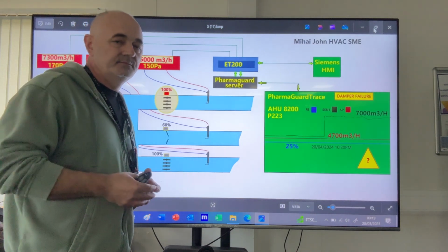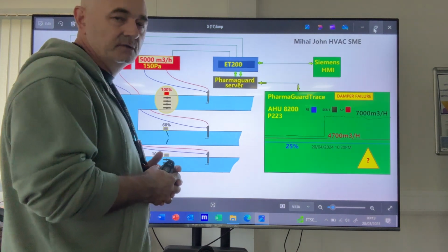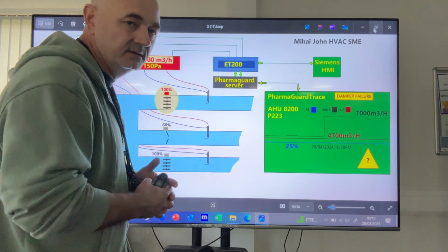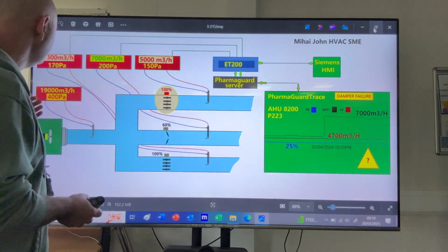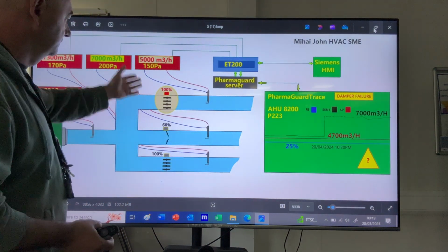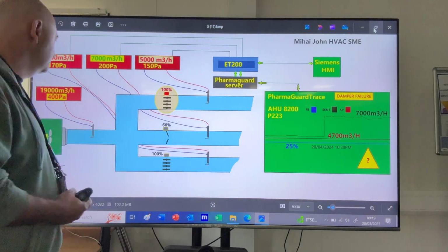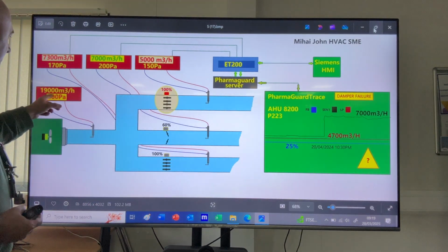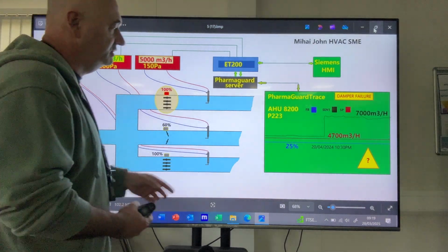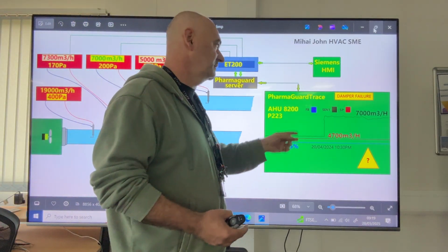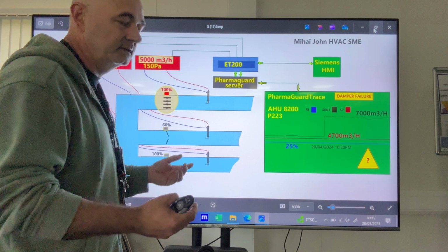So we can have an internal damage of the damper, which allows more air to pass by. Again, we compromise the airflow into other branches, and we can also see the pressure drop. But we see the shaft hasn't been changed, which tells us we have an internal problem, internal bleeding.